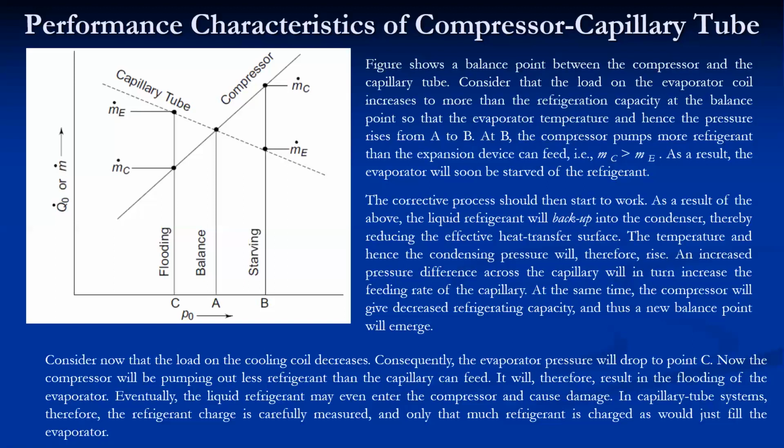So in capillary tube systems, the refrigerant charge is carefully measured, and only that much refrigerant is charged as would just fill the evaporator. An adequate quantity, neither too high nor too low, is required.